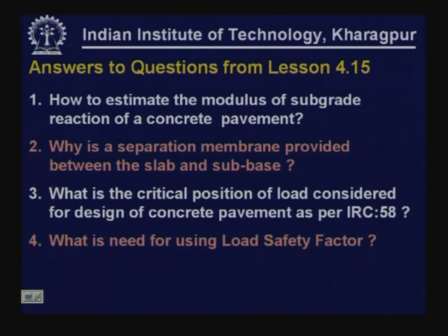Let us consider the answers to the questions we have asked in lesson 4.15, which was on design of concrete pavements as per Indian Roads Congress guidelines IRC 58 2002. How to estimate the modulus of subgrade reaction of a concrete pavement? This is with reference to IRC 58. We know that the modulus of subgrade reaction of concrete pavement has to be determined by conducting a plate load test in a particular season, which corresponds to the worst season of the year, using a 750 millimeter dia plate.